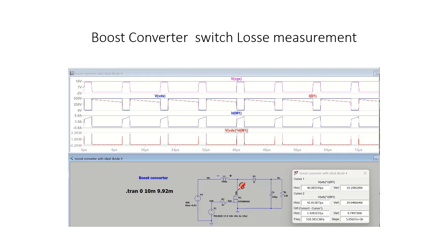When the switch is turned on, the current in the diode is transferred to the MOSFET. So all the current going through the load will be transferred to the MOSFET, and further there will be a spike in the current because of the reverse recovery of the diode. I would like to show that, and we can see that the spike during the turn on process, when the switch turns on, will be more than what you see now.